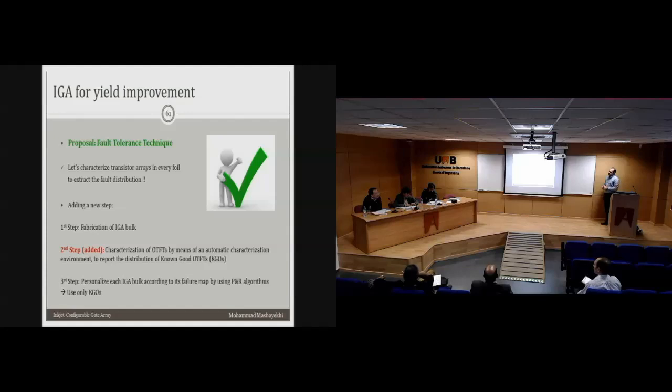And was it only ever one drop placed, or were there multiple drops placed in a single location? Yeah, that's a very good question. It depends on the used ink, the conductivity. Obviously there need to be multiple drops in order to achieve the conductivity. In the last stage that I had at University of California, we managed to print just one single drop, and when we checked the conductivity, it was not conductive.